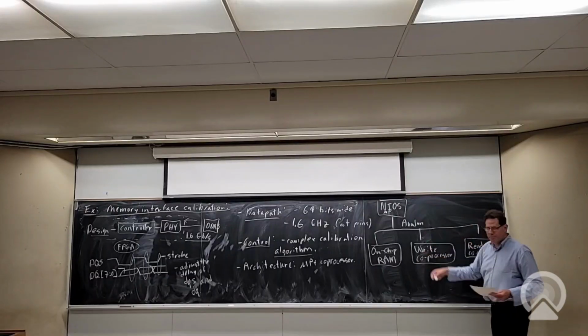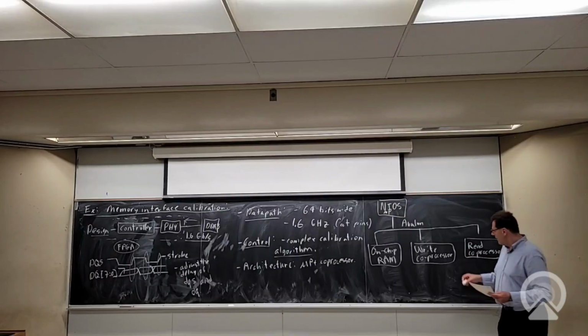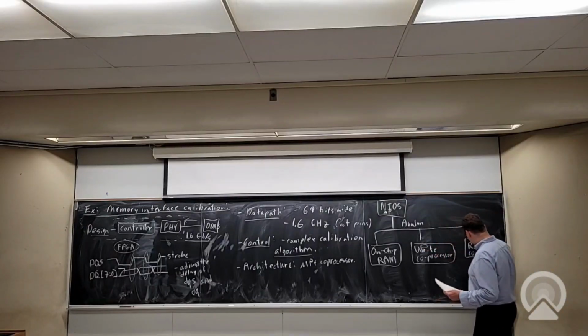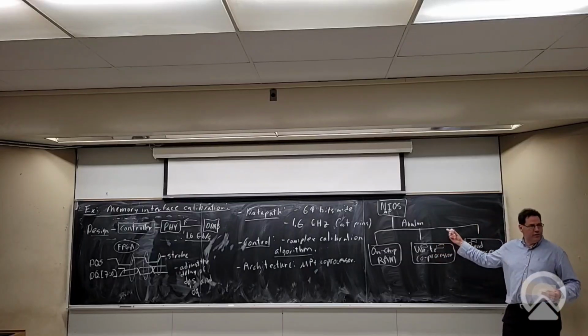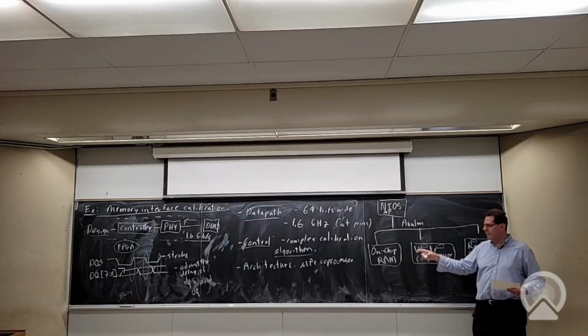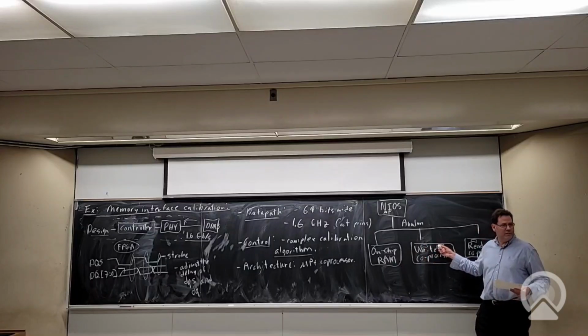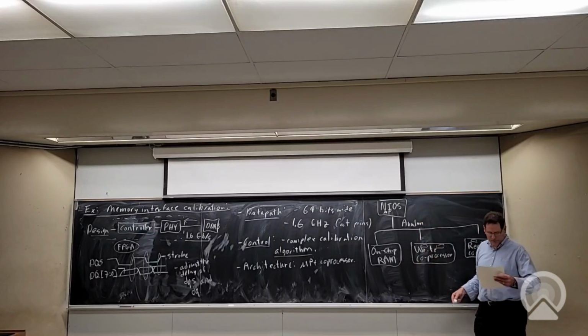Each of these is basically direct streaming hardware. They present a few registers that you can write to control them, and that they can capture their status into. So the processor can query: I sent you a command, I told you to do the following, what happened?